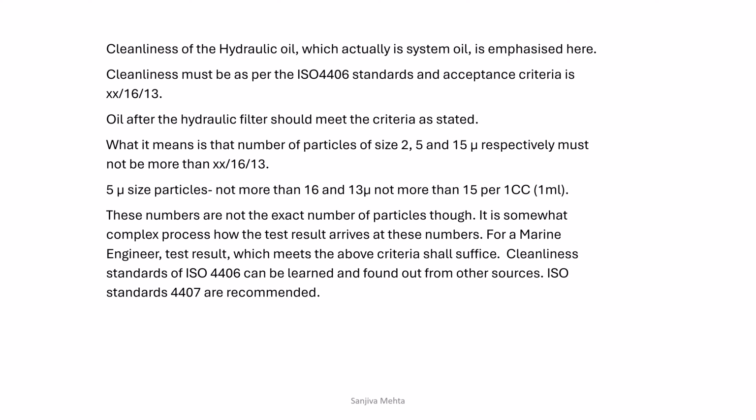So this can be checked only when you send oil for analysis. These numbers are not the exact numbers of particles, though it is a somewhat complex process how the test results arrive at these numbers, because it depends on what method they are using. For a marine engineer, a test result which meets the above criteria shall suffice. Cleanliness standards of 4406 can be learned from other sources also. Information is available on the net or in certain books, also some books in the library.